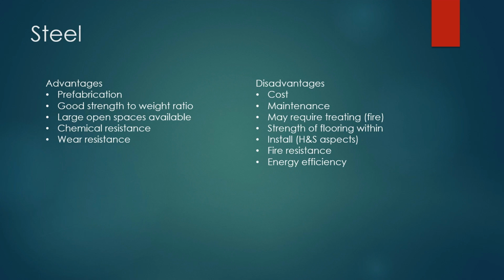On the other hand, I believe the biggest disadvantage is the fire resistance of steel, due to the fact that it reduces in yield strength rapidly when dealing with fire. This is a massive disadvantage for the end user in case of a fire in the building.